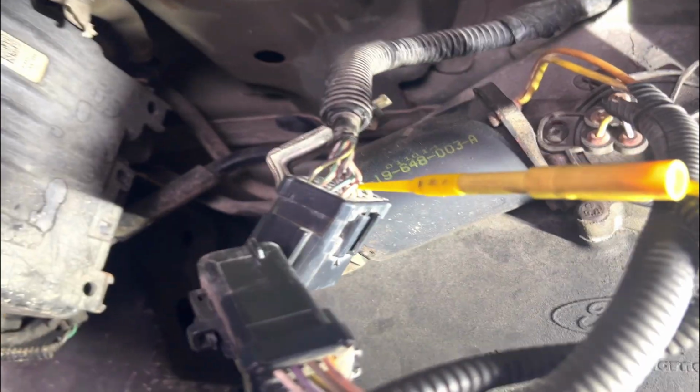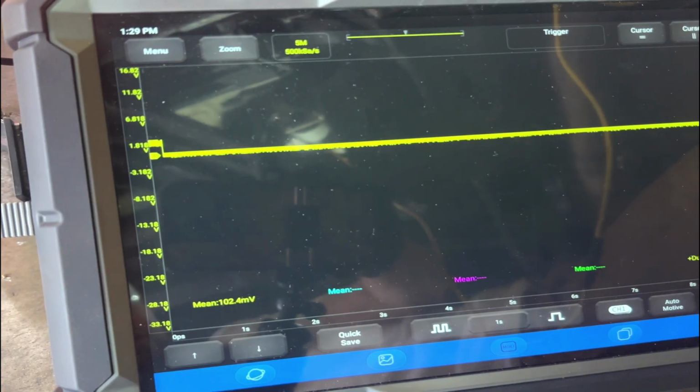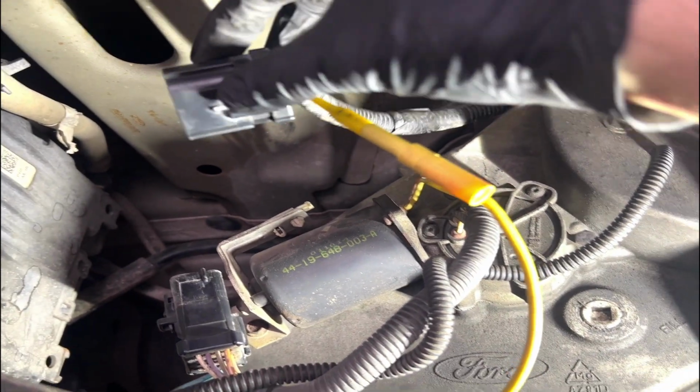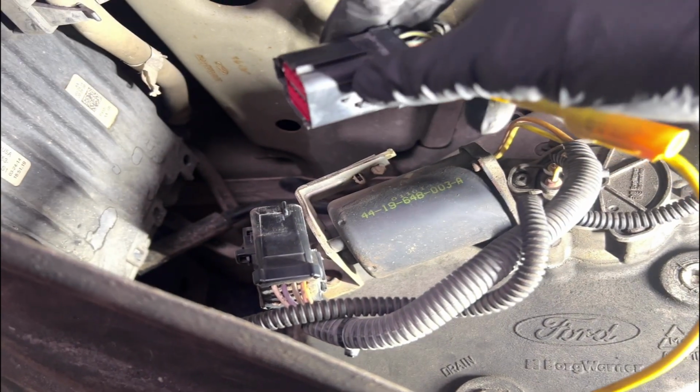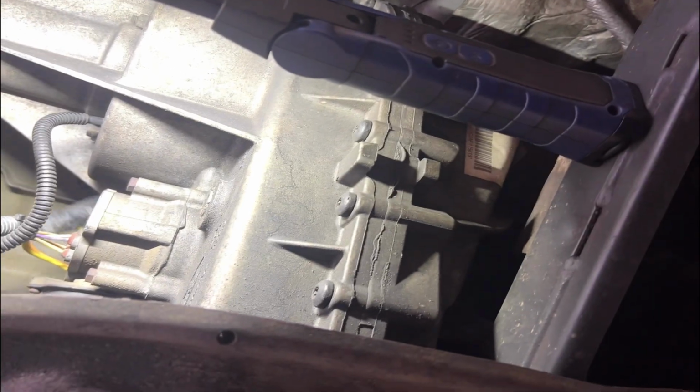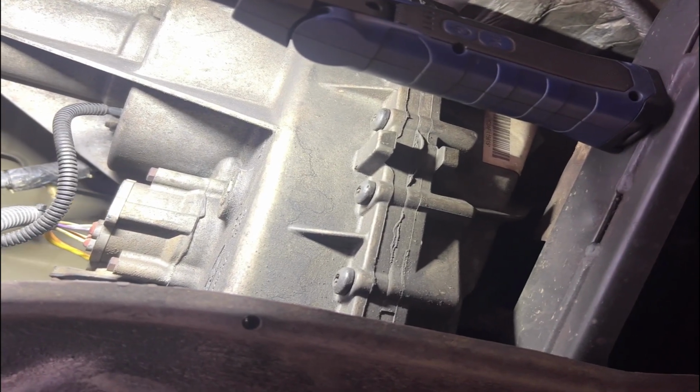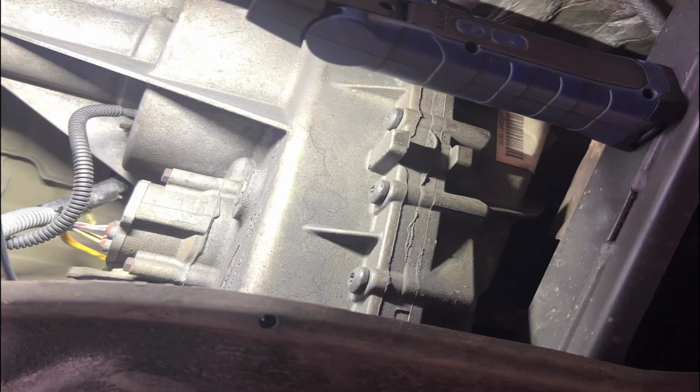Well, check that out. We are disconnected in our plug and we have dropped down to 0 volts. That means that 12 volts is coming from the motor side. So this is the vehicle side that goes up to inside the vehicle. Let me front probe this real quick just to make sure. And my voice is all goofy after I just ate.